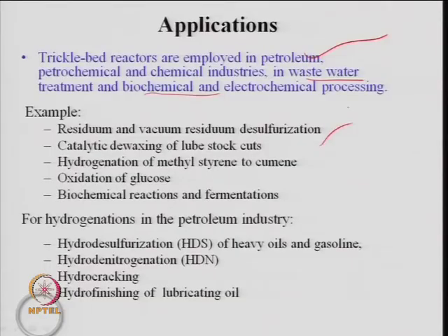So, the sulfur concentration needs to be reduced to a certain level before processing it further, say for a cracking operation, vacuum gas oil cracking or FCC cracking. So, sulfur has to be reduced. There again trickle bed type reactors are used. Same thing for catalytic dewaxing of lube stocks. That is again important when you look at the pour point characteristics of the lube oil. So, wax compounds are to be removed. For dewaxing, a trickle bed reactor is used.